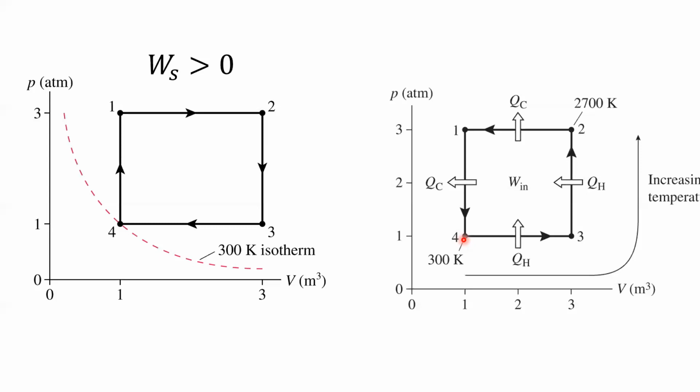That doesn't happen. You can get heat to go from cold to hot as your net result, but never along any individual process. Okay, so again, because we take the gas from 900 kelvins down to 300 kelvins and it's losing heat all the while, the reservoir it's in contact with would have to be at a temperature less than 300. So just keep that in mind.